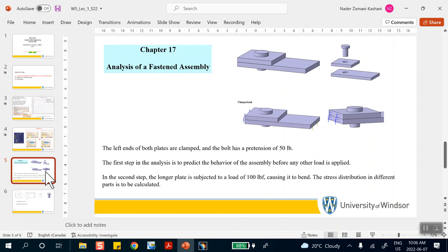Now, first of all, you tighten it because, for example, let's again think about the bolt. If you don't tighten it, it defeats the purpose. Why do you want to put a bolt there? Because the whole purpose of putting a bolt there is to clamp these two faces together, these pieces together, tight enough so that they don't become loose. That's really the purpose. So you don't do that in a random way for a critical problem.